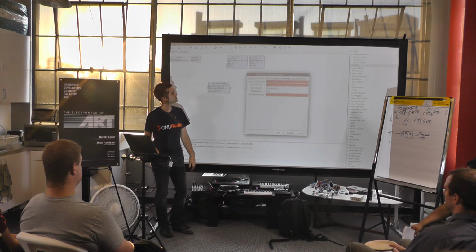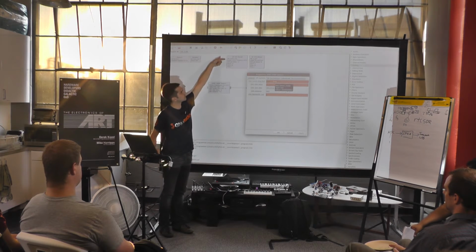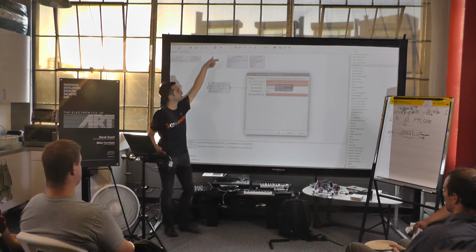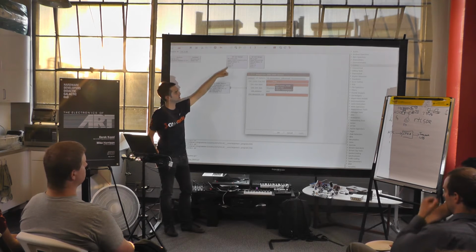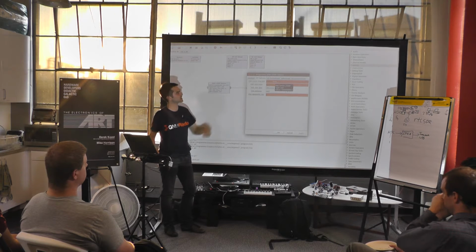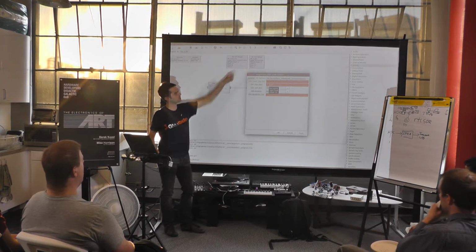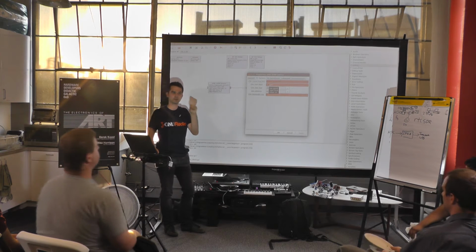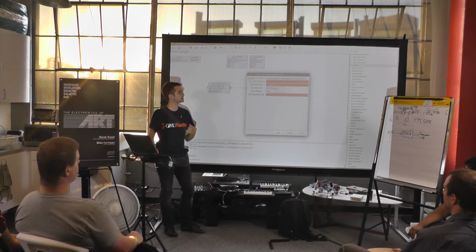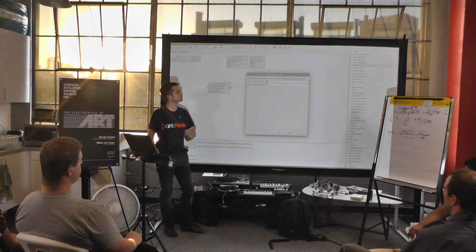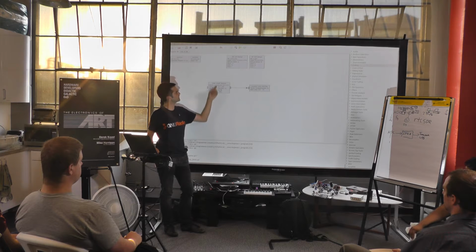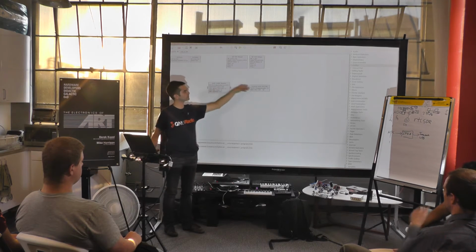And then in RF options, we have another one, which is center frequency. And so this is going to be a slider, and that'll be all auto-generated for us, called center frequency in megahertz. So I'm taking that and multiplying it by 1 million. And then for RX gain, that's going to be our other slider. So that'll adjust how much gain we put onto our radio. And that'll determine basically how many signals we can bring in. And that's all advanced stuff, which you don't need. So this is sourcing the samples, sourcing the signal, and we're going to run that right into a sink.